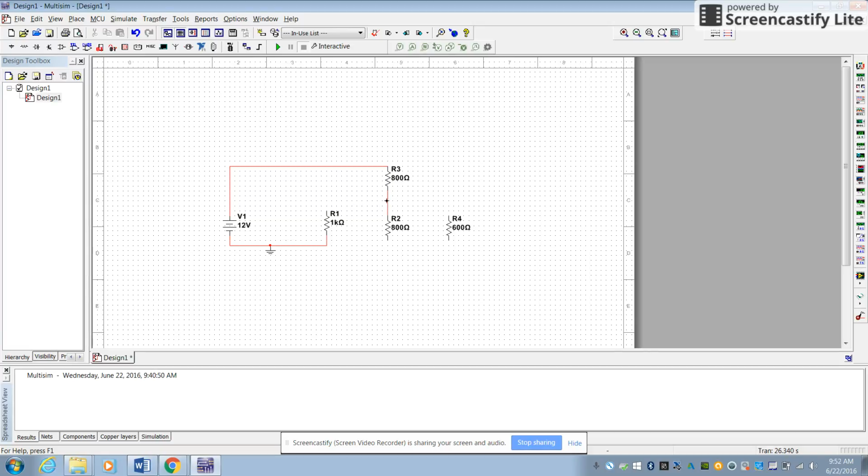You got to make sure you get the little dot tool as well, otherwise you will rearrange those wires. When you have the angly wire tool like that, that means it's going to let you drag and rearrange that wire. It's not what you want 90% of the time. Why they put it in there, I don't know. Some people like it. I just prefer to delete and remake a wire.